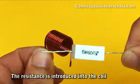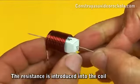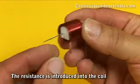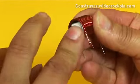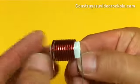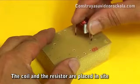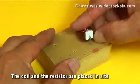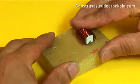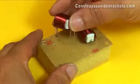The resistor of 10 ohms, 5 watts, must enter perfectly inside of the coil. Then fold our terminals downward. We insert the set, formed by the coil and the resistance, in the PCB. We put the other set.